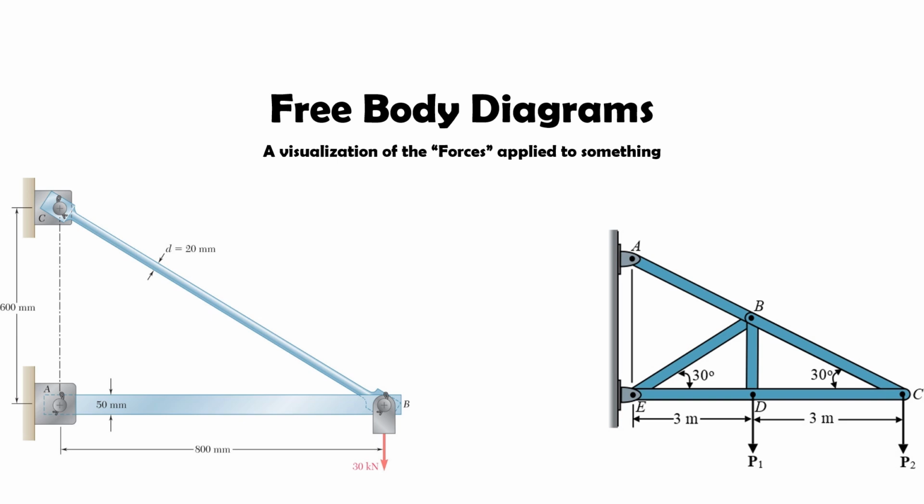Look at some truss or frame systems and how the pins have to take a reaction force. For that matter, what is a reaction force? Well, a reaction force is simply a force that has to exist in order for a system to remain in equilibrium, or stationary. Let's see what happens if we remove a pin or two on these truss systems.